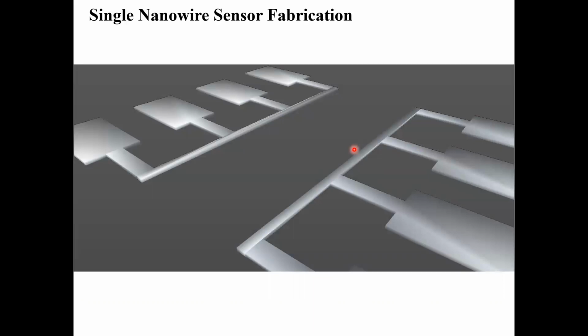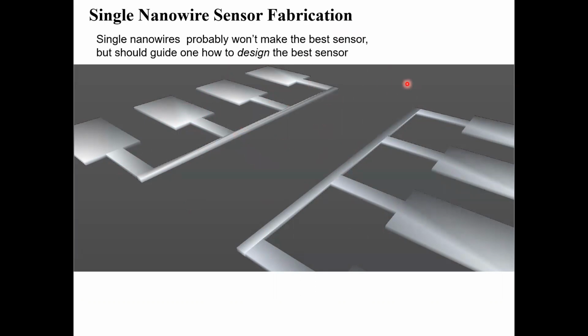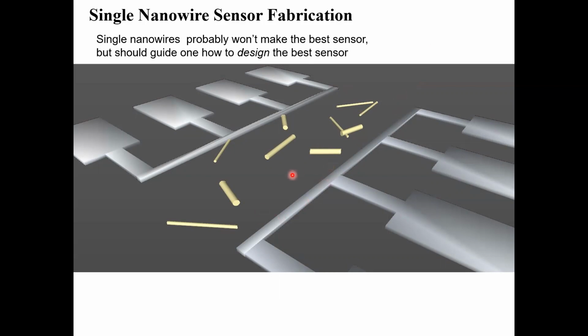Following along the direction of systematic studies, one can start with this lithographically refined platform made out of copper or gold or platinum with the contact pads there. And then you will spread your nanostructures on top of that platform, something like this. So you collect all this nanofiber, make a suspension, put a few droplets of the suspension onto this platform, and then dry it out and fire it. And then you have these nanostructures distributed on this platform.